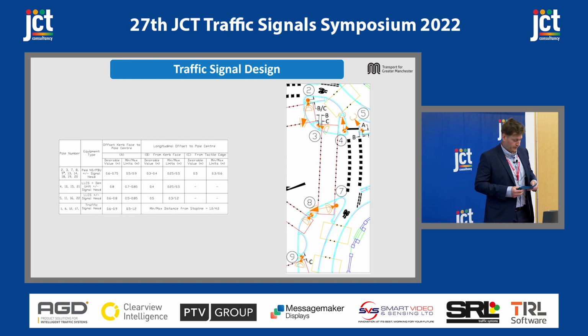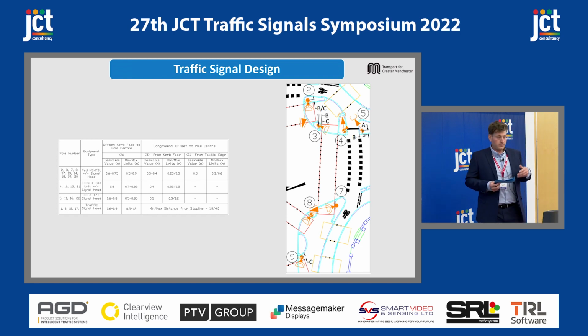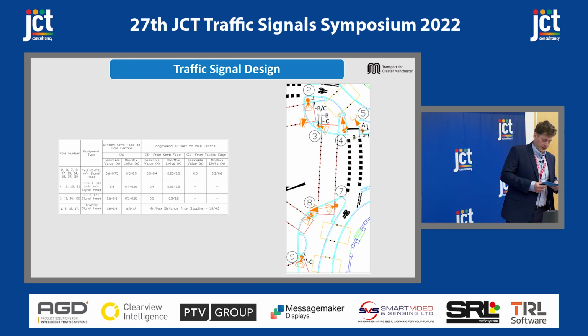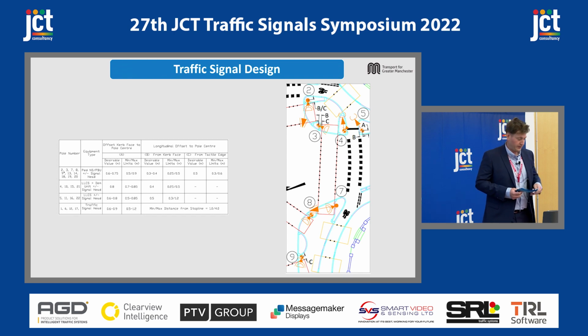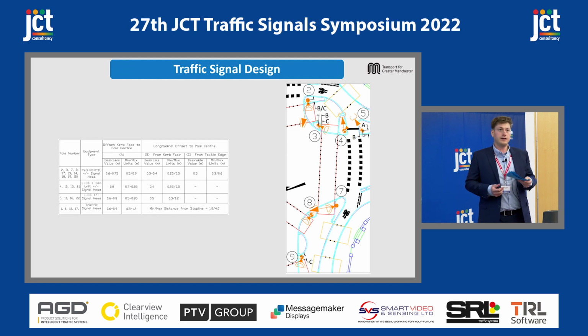Other traffic signal elements that are important with regards to the horizontal design are cycle phases. So at TfGM, our preferred arrangement is to position the low-level cycle signals to the near side and the off side of the cycle track, creating a cycle gateway, much like traffic phases. And this arrangement also helps in the event of a lamp failure.